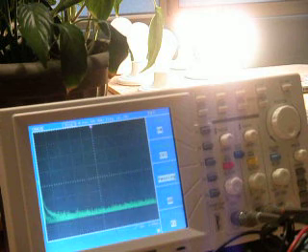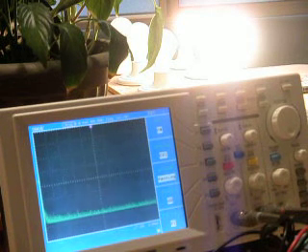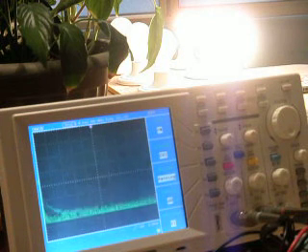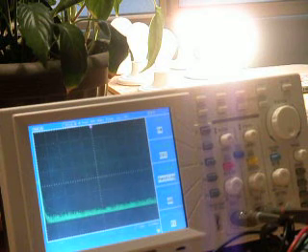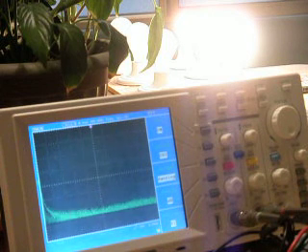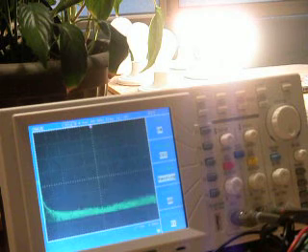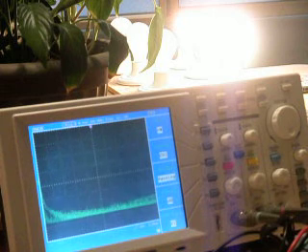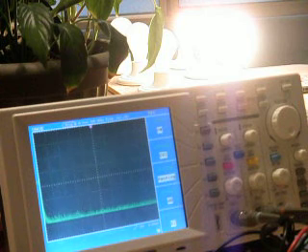So that's what harmonics is. It's something you need to be careful of. Because of these effects, I don't recommend that you have lamp dimmers in your home, and it's something to be aware of. If you have noisy electricity that's giving off electromagnetic interference, then it's probably in your interest to contact an electrical engineer who is familiar with power quality, and have him come into your home and inspect the voltage and current waveforms, and you may find some very interesting stuff going on in your home electrical system that you may want to get rid of.